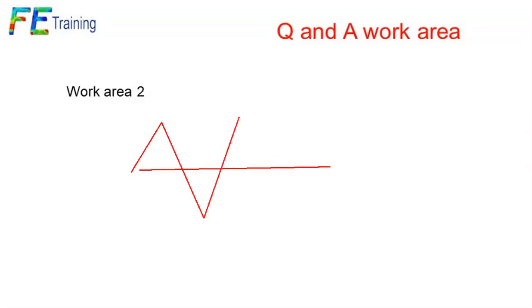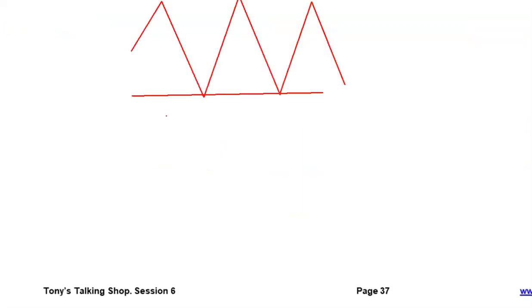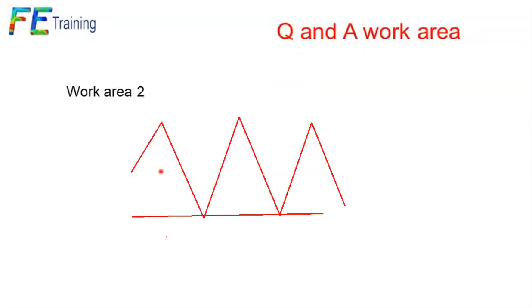So what happens here is that we can actually put a correction factor on. If we actually have the mean stress is not 0, we drop it down to here as we saw. So in each case we're going from 0 stress to max. That's going to give us a different value of R, which is essentially associated with the mean stress level. There are correction factors we can use.